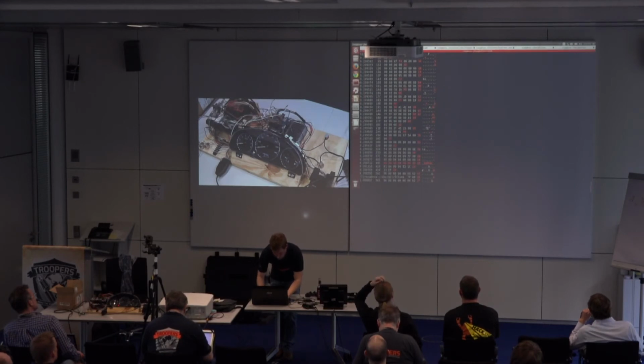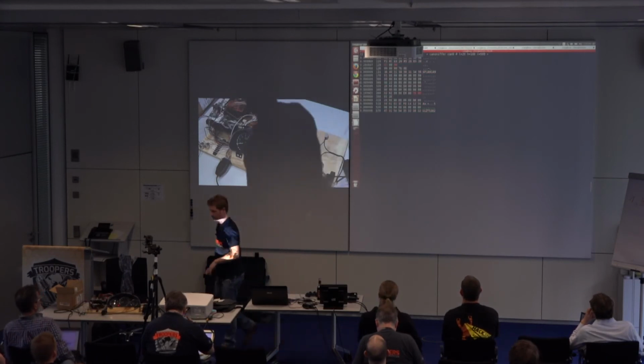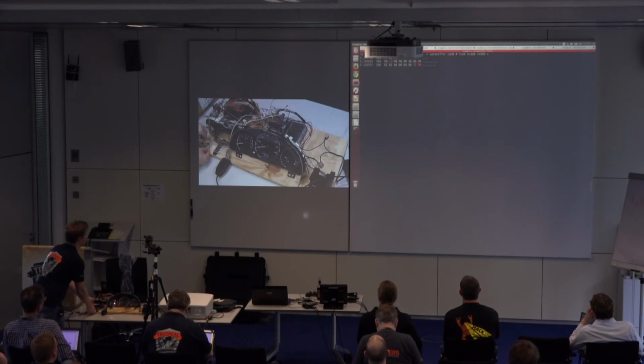Yeah, let's do it live. All right, so that's just normal CAN 0, not virtual CAN 0. So let's do fuel first. Let's figure out if I start changing it, since we have just a few on there, we can see right away like a new one popped up. We're at full tank right now. Let's drop it to no gas. And so it goes down, and there's no gas. So it's 308 with 0. Second byte controls the gas.